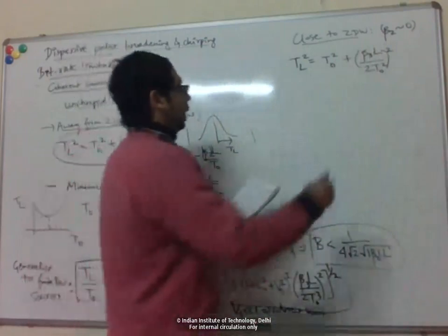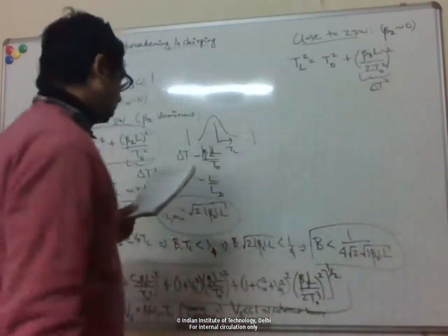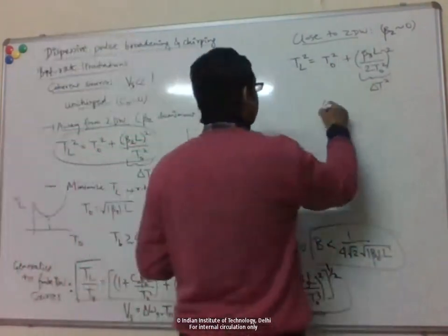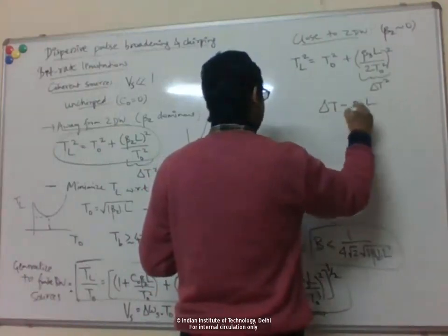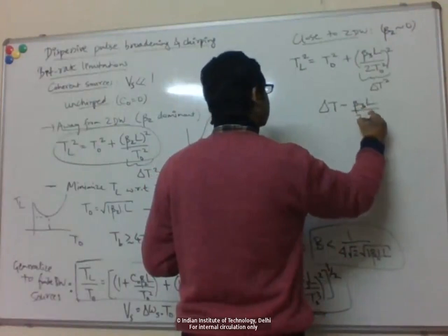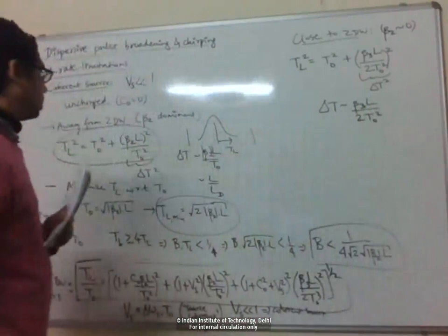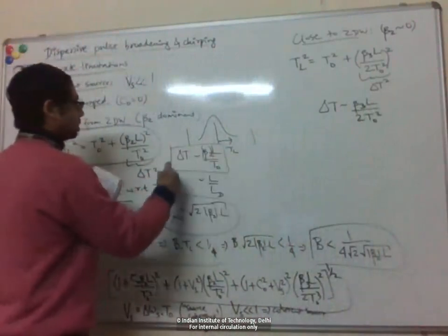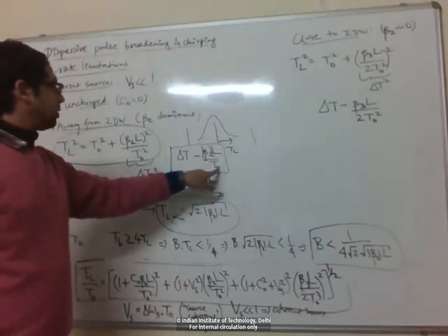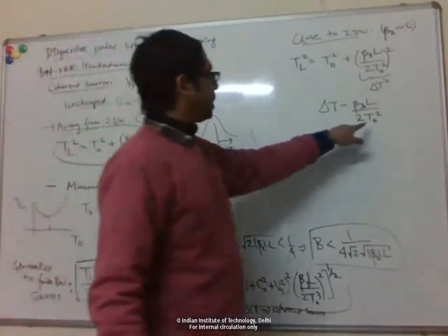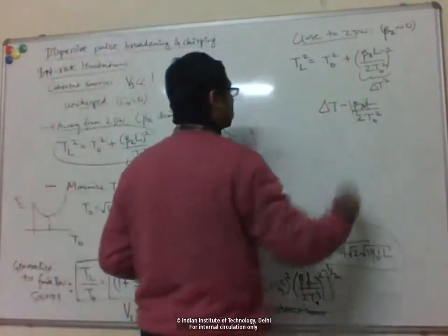Okay. Again, now we can define this as some broadening factor. So now the broadening you can see is the beta 3, third order dispersion, times length divided by the square of the pulse width. Okay. So in this case, it was beta 2 times length divided by pulse width. Now we have pulse width squared in the denominator.